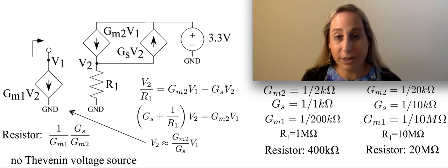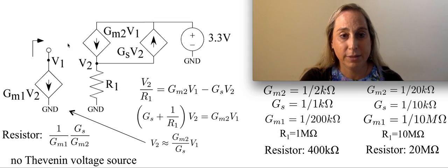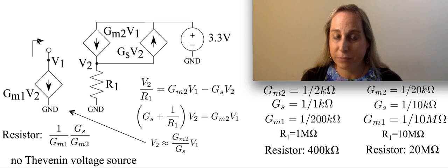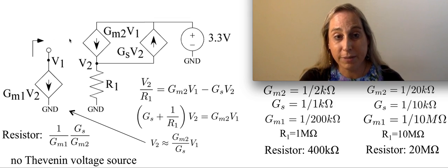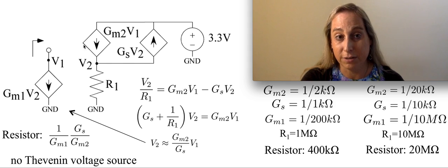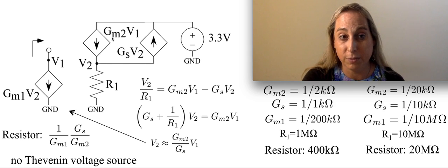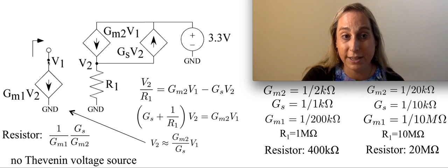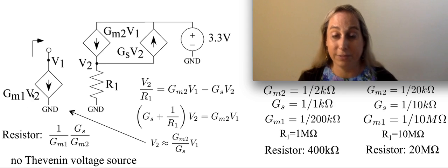So it's a very interesting question to see what happens when I look at this representation. What would I expect when I look at the effective behavior looking into this V1 node? What's interesting is that these two current sources have an interesting play to them. The V2 is certainly related to what's going on locally, but this V1 is related to this voltage. And then notice that what happens here is related to V2. So you get this sort of double coupling of things.